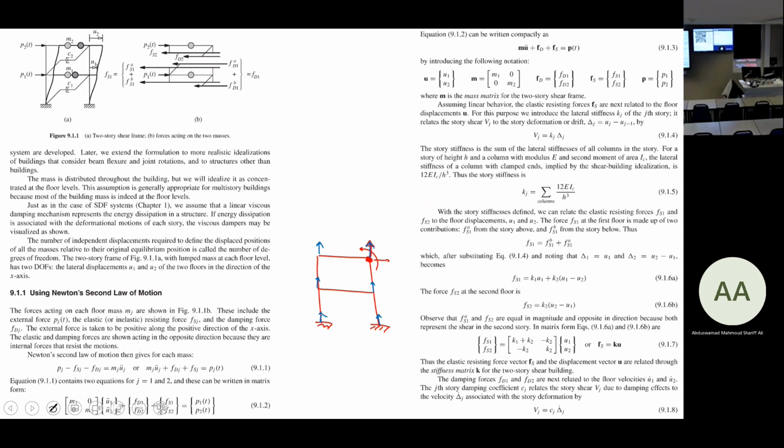Why am I assuming this? Because the axial stiffness of the columns is very big. If you really model this in ETABS and calculate those displacements for any building, you will see that if your lateral displacement is something, this displacement is very small in comparison with those displacement values. But this is a rational assumption to take into account here.